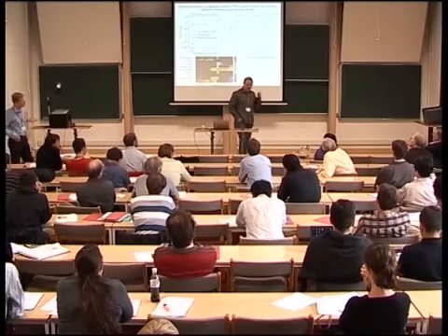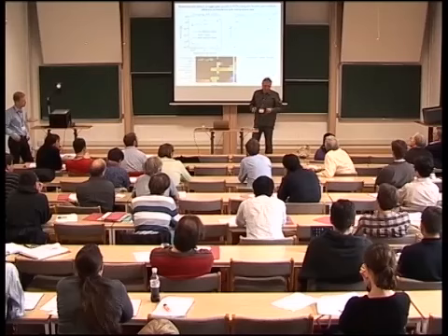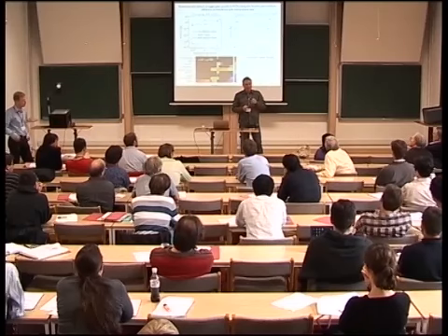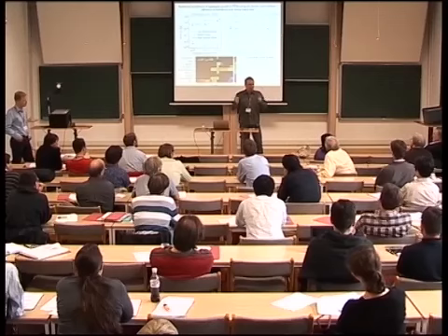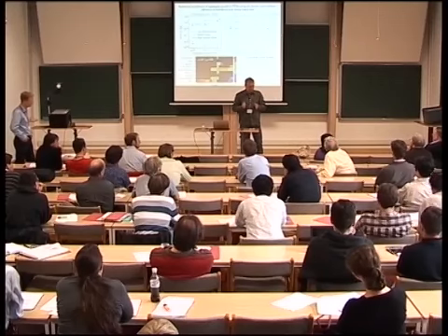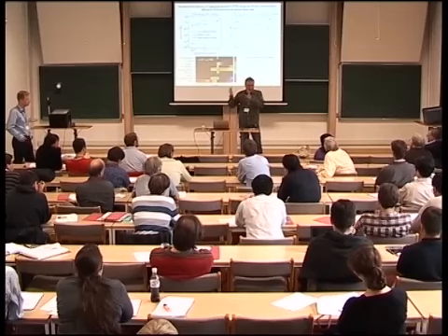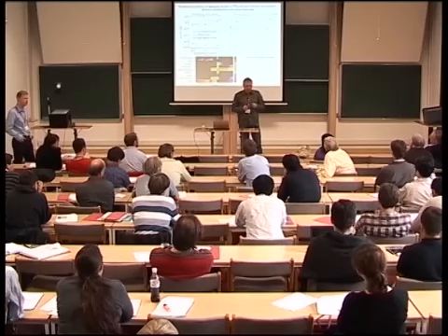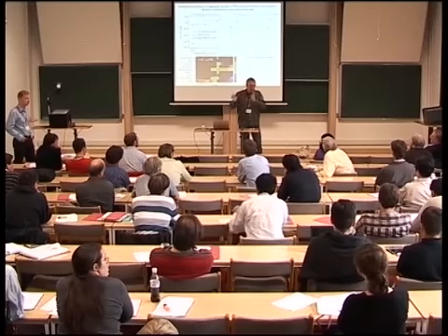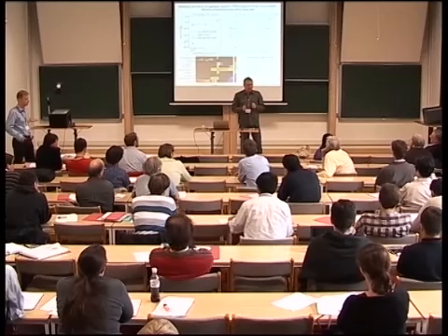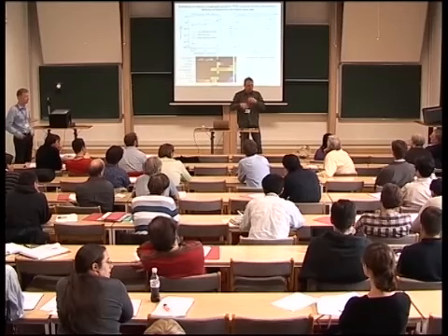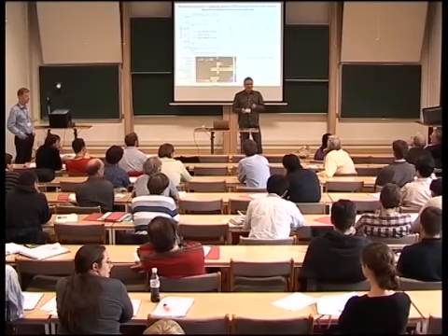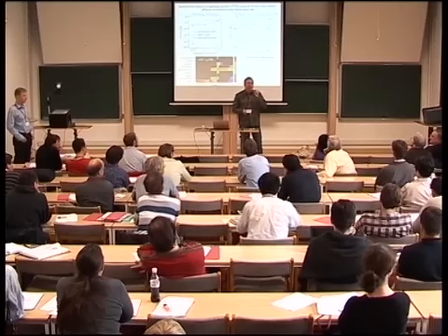To answer your first question, we did experiments with different materials. I only showed you the bulk of the experiments, which was done with these SiO2 spheres. We have irregular SiO2 particles from 0.1 to 10 microns, and we can make very high porosity samples with those. Qualitatively, there's no difference. The velocity may shift by a factor of 2 or 3 or so. Usually those aggregates are more fragile, so they are much harder to produce. However, I think this is a relatively minor effect.